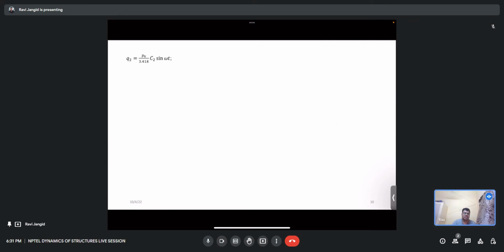Now we determine the overall response. For these modal responses, U1 can be determined as phi 1 Q1 and U2 as phi 2 Q2. U1 is also the response corresponding to the first mode, and U2 to the second mode. So for U1, the mode was 0.7071 Q1.